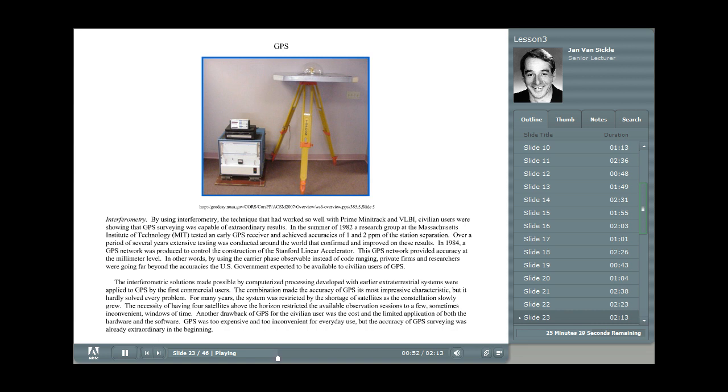And they had to be brought together, and their clocks had to be synced up. Their oscillators had to be synced up because, of course, we didn't have access to the navigation message since we weren't using the codes. It was a completely codeless receiver. The antenna here was a meter square of aluminum, and you can see the dome with the dipole antenna on the underneath part. And of course, the antenna was cabled to the receiver. You can almost see the tape drives on the front. We used tapes to record the observations.